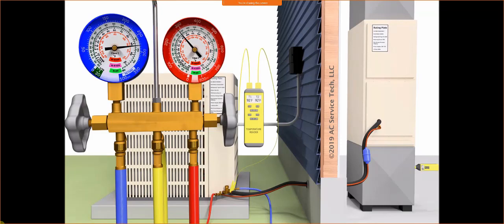So before you turn the air conditioning system on and try to check the refrigerant charge, you want to go ahead in the inside of the house and make sure that you check the indoor air filter to make sure that it's clean, and you want to check the airflow speed. So what I typically do is I pull the disconnect at the outdoor condensing unit, and then I go inside, check the air filter, and I also check the blower speeds at the control board.